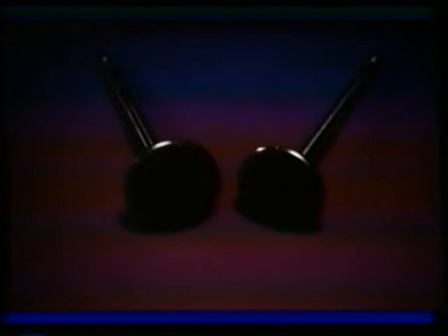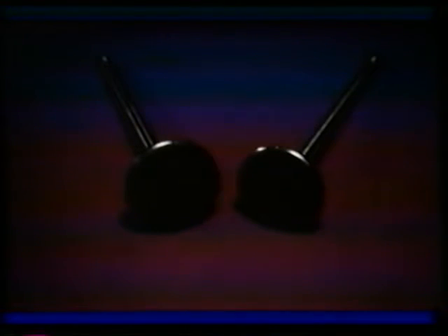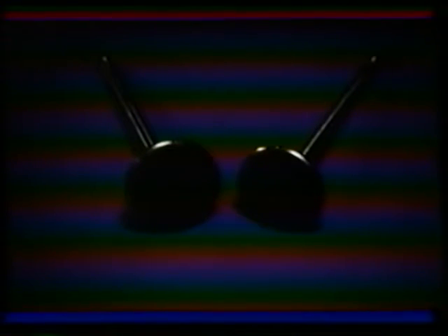It evens the wear pattern on the valve and seating face, reduces buildup of deposits, and keeps a uniform temperature on the valve head. The design of the 3200 series engines permits their valves to rotate slightly without such a device. In addition, intake and exhaust valves from the same engine are not identical. In most cases, intake valves will be larger to aid the engine's breathing. The high cylinder pressures after combustion will readily vent the exhaust gases, even through a smaller port. Lastly, exhaust valves are subject to much higher temperatures and are often made from different materials for added heat and wear resistance.